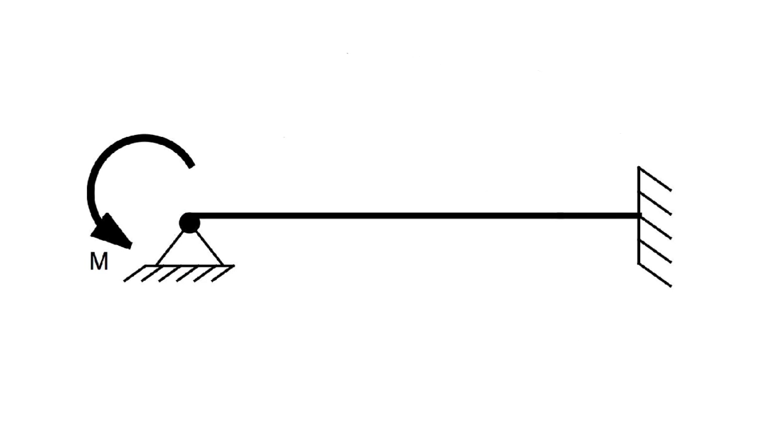Let's now sketch this case by hand. We again start by drawing stubs or small line extensions at each side. We choose an arbitrary but large slope for the stub on the left end so that the shape is clear. On the right side we draw a small horizontal stub. We want to have the maximum height to occur at about a third the length from the left end, which is the theoretically exact location. Well, we locate that approximately and we mark the maximum level with a line at about that distance.